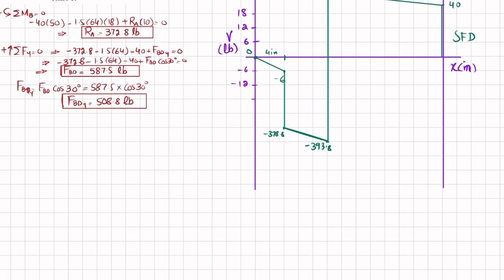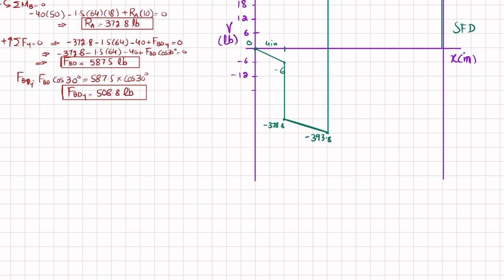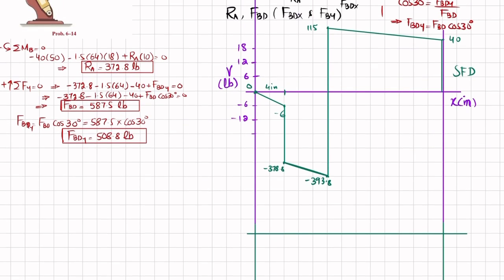Now we'll move toward bending moment diagram. So for bending moment diagram, I will extend it. Clear? And here you will have to pay attention because we will use the simplest method. We know that this is moment and the unit will be pounds into inch, and this length x is in inch. So first, the area under the shear force diagram, this area, you can see is a rectangle.